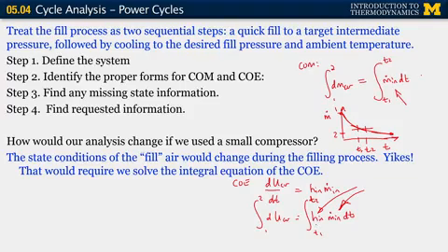So the state within the fill chamber could be changing, and typically we would look at how the enthalpy changes as a function of temperature. So how does the temperature within the tank change as a function of time? And we'd have to have that convolved with the mass flow rate changing as a function of time. So you can imagine these transient analyses get very sophisticated, with not just time variation within the control volume, but these fill problems or draining tank problems also become very complicated when we consider the system to be changing during the process that we're concerned about.